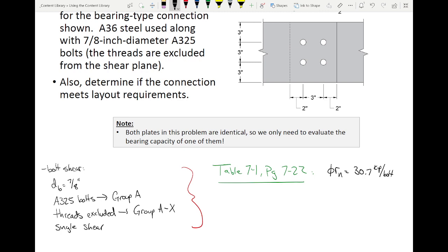So is double shear like 3 plates? Yes, and that happens in splices, right? When you have a beam and you have a plate and a plate on top and you yank it, you have 2 shear planes. That happens all the time. Double shear conditions are very common. If you ever see a beam splice connection in a bridge, look at the flanges. The bolts are in double shear.